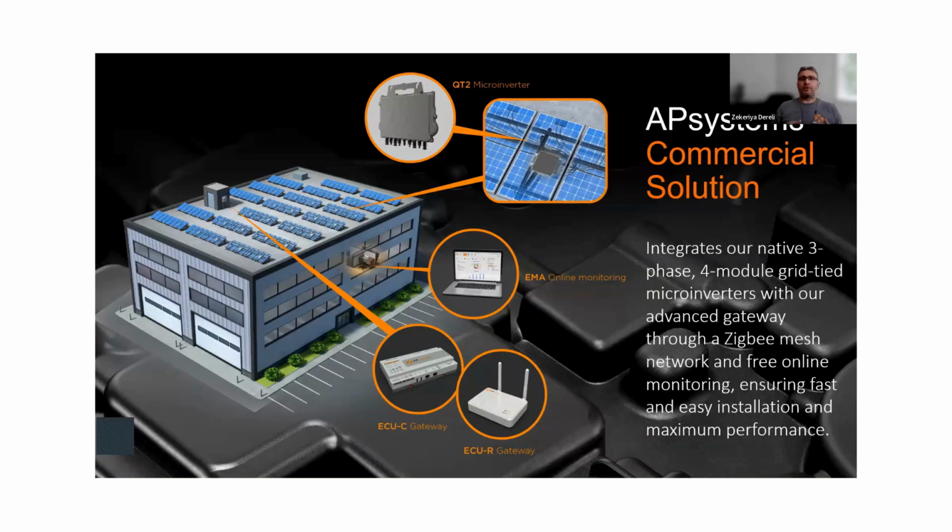We have quad for the simple fact that you want to reduce the BOM, right? You want to have less equipment. So four is an ideal number, really. I mean, anything beyond that is just going to make life a little bit more complicated, I think. With four modules, it's not that difficult to wire them into the micros, especially for the commercial applications. And again, the communication is still the same. It's Zigbee, a wireless communication. You get your ECU communicating with all the inverters wirelessly.